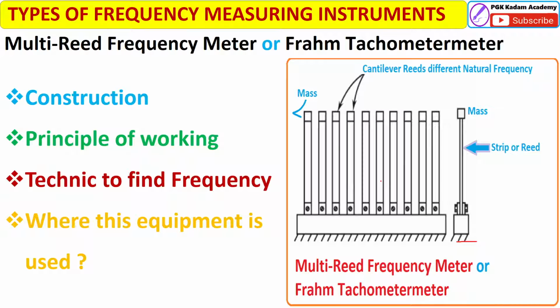When this instrument is mounted over the vibrating body whose frequency is to be measured, the reed whose natural frequency is nearest to the excitation frequency of the vibrating body will vibrate with the maximum amplitude due to the resonance condition.